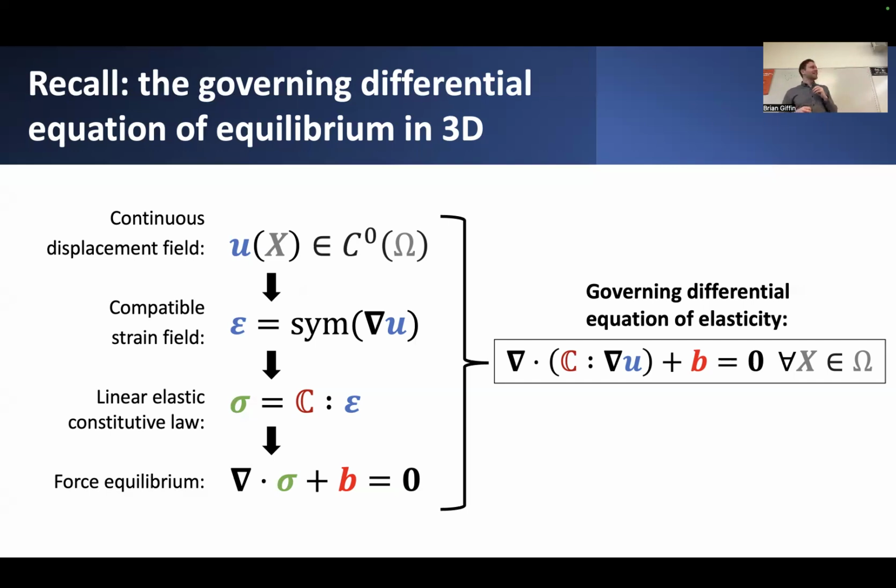And specifically, in the case of linear elastic deformations, we could define this so-called small strain tensor, represented by epsilon, also a 3x3 array, but it's symmetric. And in fact, it's defined as simply the symmetric part of this displacement gradient tensor.